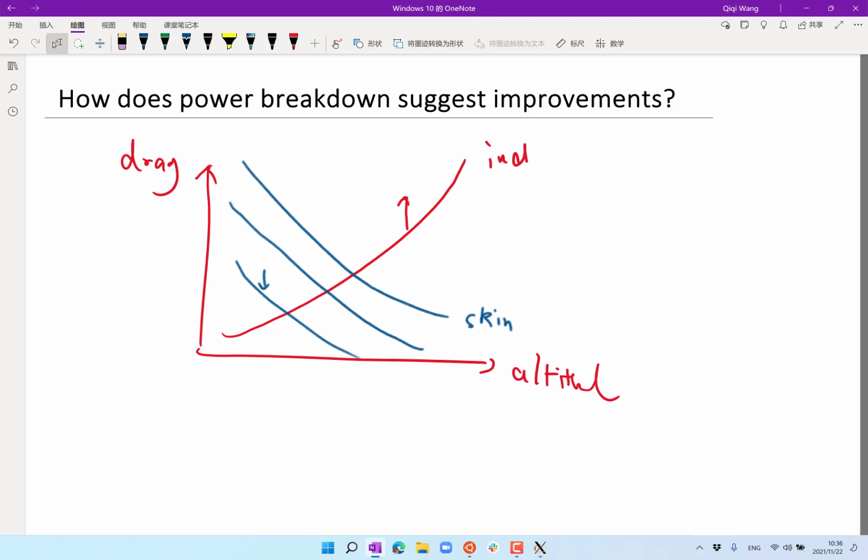And once you decide on both, you have enough knowledge to design an airfoil. You know how much lift you have to provide, and at transonic or supersonic conditions you have different requirements. Basically, the lift coefficient constrains you from the low speed side, and the drag constrains you from the high speed side.